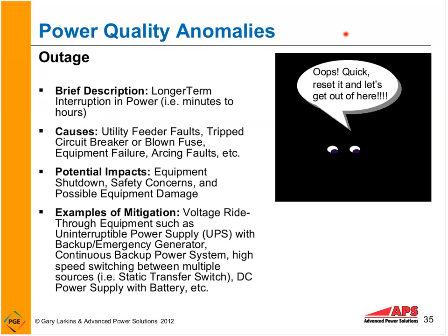Outages. Of course, sometimes we have that car that hits the pole, or we have a fuse or a breaker trip in our facility resulting in an outage. Now, if we have critical equipment, we may need an uninterruptible power supply that can provide short-term ride-through till we can get the issue resolved, or we may have to have a UPS system with a backup generator, or maybe we just have a backup generator there. We can take a short interruption, but we can't live without the equipment for hours if we have some type of, let's say, cable failure in our facility that may take longer to fix.